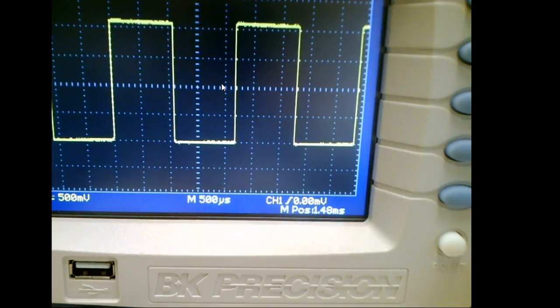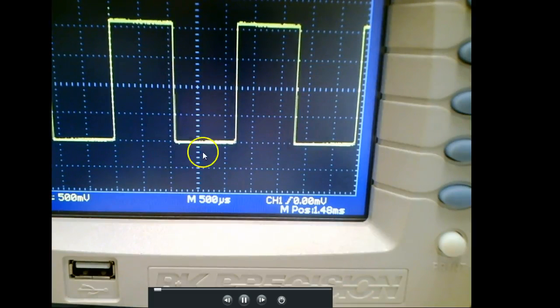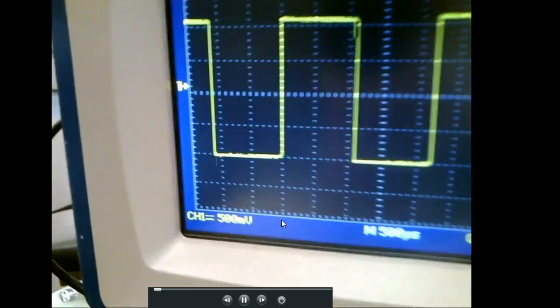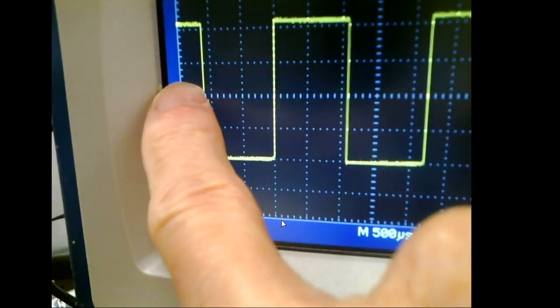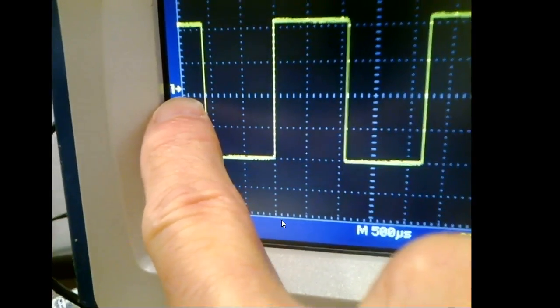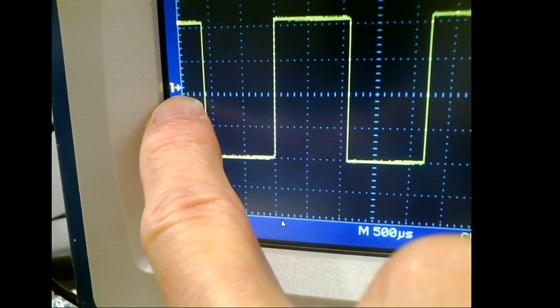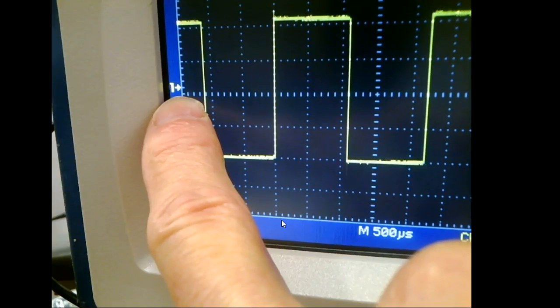So what it means is that they expect you to have a little bit of knowledge of trying to read an oscilloscope. Now, what advantage does an oscilloscope have over a meter? An oscilloscope shows you what's there relative to time. A meter does what? It averages everything out. What would my meter measure if I put it on this thing right now? It's going to measure 0, because this is not DC, guys. This is AC. I don't know if y'all can see my channel 1 marker right there. So this is 0 reference right here. And what a meter does when it sees AC, it averages out and it gives you 0.